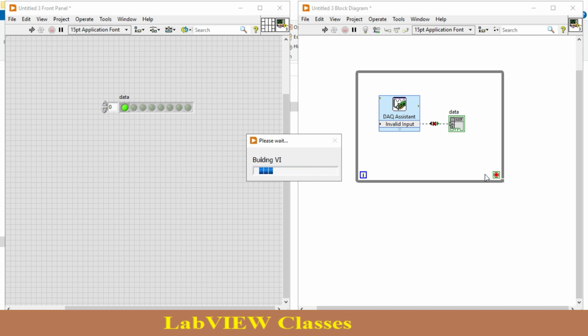So in this case I just need a breadboard, because I need 5 volt values. On the board I have only one port. I just connect a jumper wire to it and put this 5 volt over the breadboard. I just show you. So in this case I just want to read 3 signals. I connect 3 jumper wires with the 5 volt signal to my different pins, 0, 1 and 2.